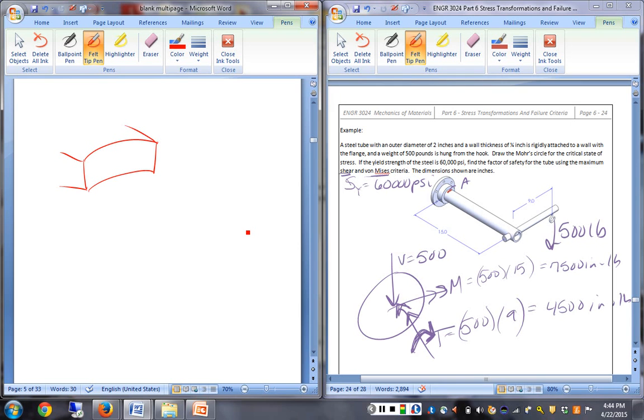All right, so at this top, this is at point A. We would have normal stress coming out from the surface. And we also have shear stress going which way? We're twisting it like this, so my shear stress on that cut surface needs to go that way, which means I also have one going back that way.